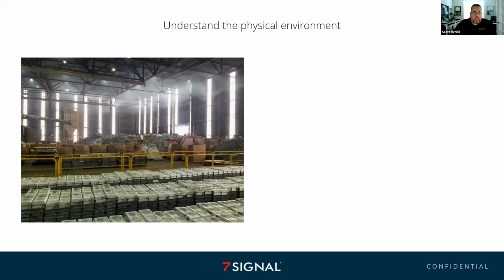And because you know what the materials are, you know it's going to be a highly reflective environment. You're going to have to make sure that you plan for lower power levels, smaller cell size. You want to reduce that multipath as much as you can. Because in this particular project, yes, it's for inventory control, but the driving force behind this is the body sensors that the guys around the smelter will be wearing to monitor them while they're working in these conditions. So these are safety, and this is a much higher priority than whether or not you can watch cat videos on YouTube.